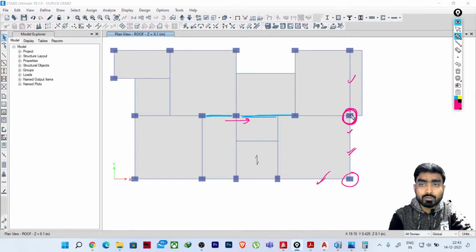So yeah, you do not have to provide higher stiffness in this orientation because in this orientation the moment will be balanced. But for this corner column, in this direction we don't have anything. Right, in this direction we have load, in this direction we have load. Now you can orient it anyway, because here also you don't have anything. It cannot be balanced in both the sides, so you just have to check in which direction it is critical, or maybe it is required for you as per your room placement, and you can change the orientation for this